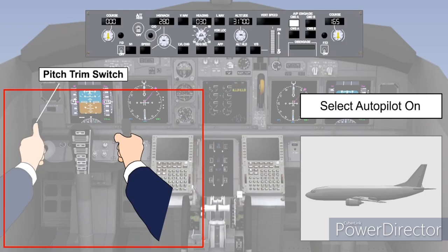When the pilot is flying the aircraft with the autopilot disengaged, he will trim the aircraft manually. Fly-by-wire aircraft have a full-time auto-trim system that operates in autopilot and manual control. Most airliners have a trimmable horizontal stabilizer and elevator combination for pitch trim and control. If the auto-trim system fails, the autopilot will not remain engaged. It cannot be allowed to control the aircraft if it cannot trim in pitch. If the pilot operates the manual pitch trim when the autopilot is engaged, the autopilot will disengage.